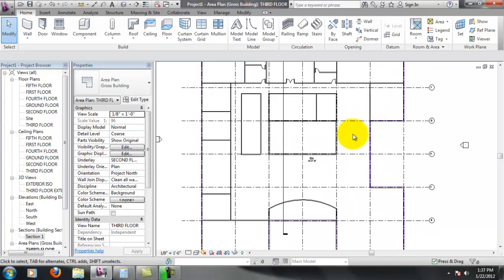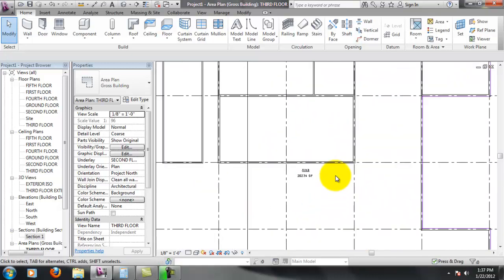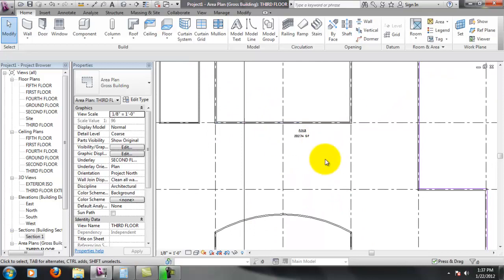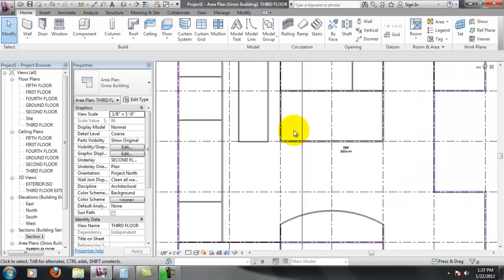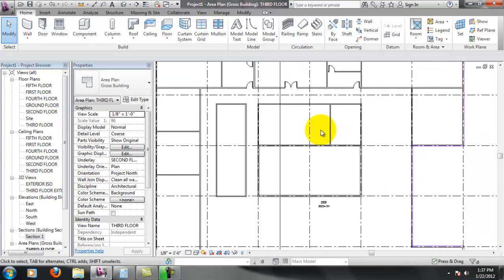So what I am interested in is roughing in the amount of toilets that I need. In order to successfully calculate the amount of toiletry objects you need, you have to go through the occupant load and figure out how many people max will be on that floor, and the maximum amount of people on that floor, as we just discovered, is going to be 200. So if you flip through the code manual even more, you will find an area that has the required toilets for a business type class